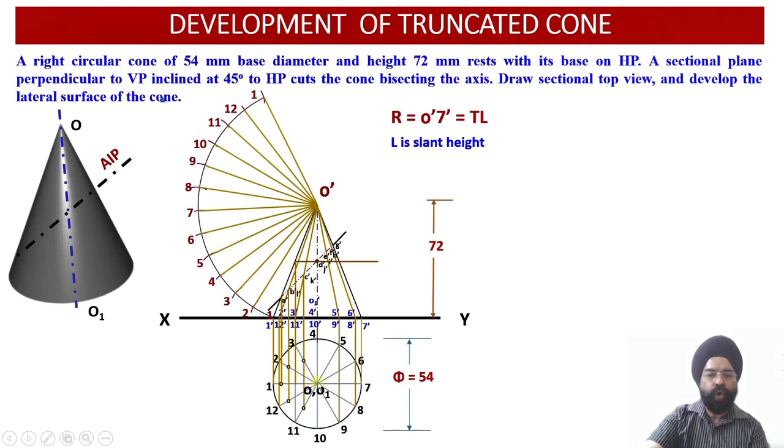That is on O1, I need to bring this point. The moment I obtain this point, I have transferred this radius. What I have done, I have transferred this radius over here. I'll keep the needle of my compass here, open the compass this much, and transfer the radius on either side, so that if I'm looking from this side, these 2 points, this radius and this radius, are available to me.